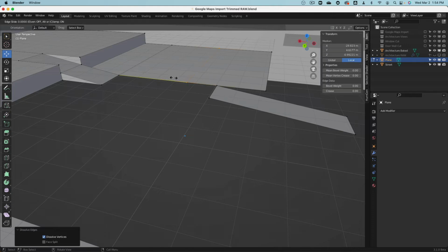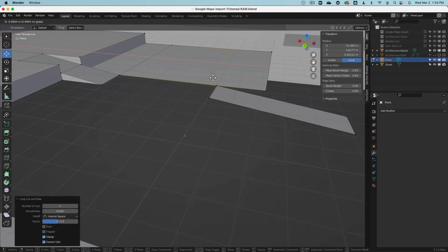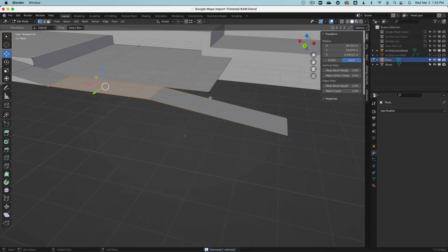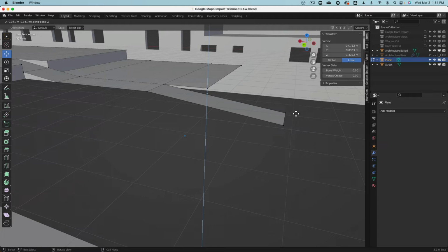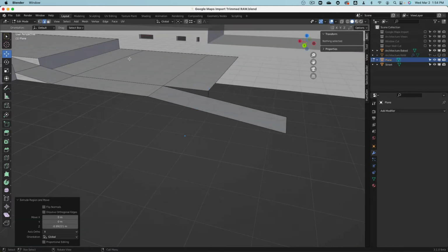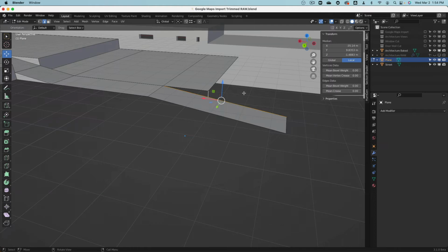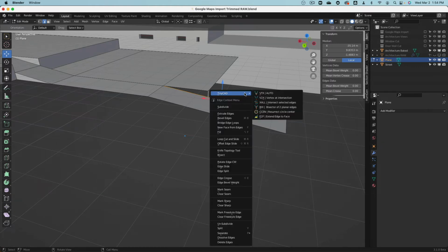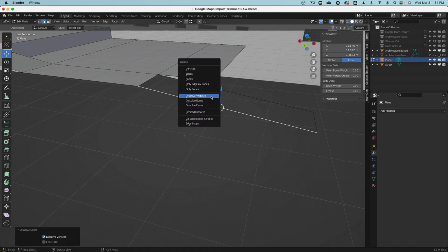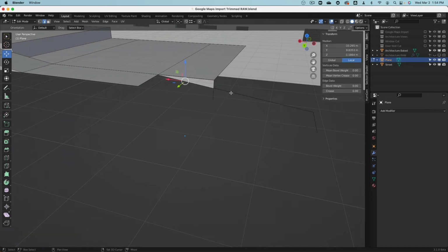Control R, click, move, snap, A Q, merge by distance, fill, thank you. Now U, E and Z down, hold Control onto this point. You see, yep, correct, same command there, right click, intersect, and then we just rebuild these faces, this here, X and dissolve, no, X and delete edge.